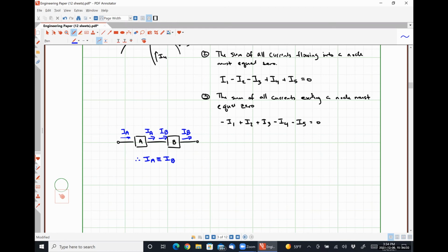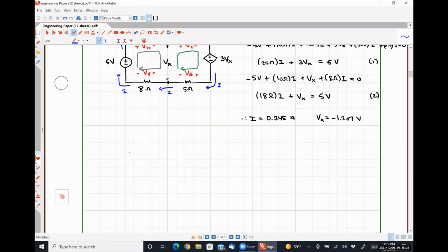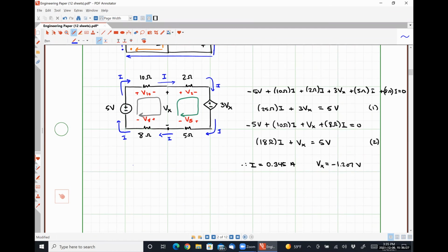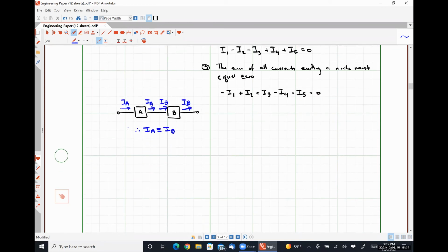So all that means is that when two elements are connected in series, they have to carry the same amount of current. Okay. So that's another way for us to define whether or not things are in series. We talked about last Wednesday that elements were considered to be in series if they shared a single point of interconnection with no branching paths. This is that situation exactly, but we can now expand it to contain multiple elements, where let's say A was connected in series with B and B was connected in series with C, since they all carry the exact same current, we can treat them as if they are all in series, okay? Which is exactly what we did in this example problem here. So we used Kirchhoff's current law accidentally just by using logic effectively. All right, so now let's circle back around to an example problem.